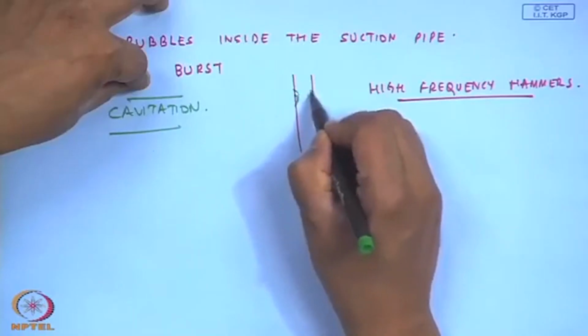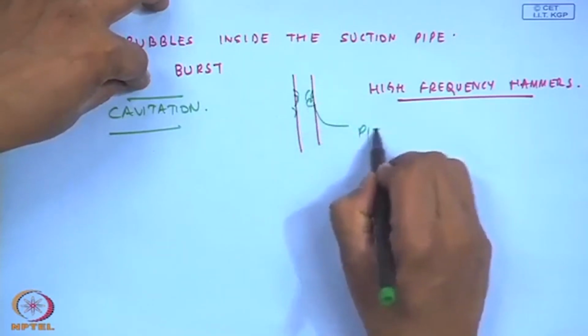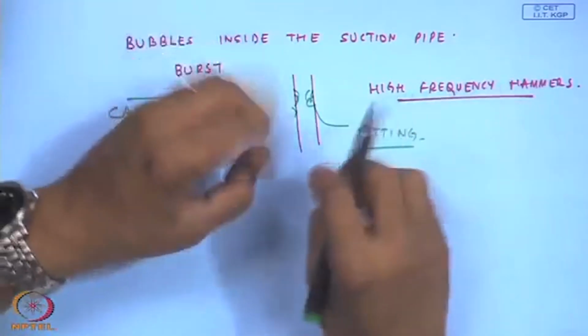The inner walls will get pitted, because when the bubbles burst they release energy as if they are hitting. If this goes unnoticed they will weaken the structure, and then a lot of the surface will become weak, and it may eventually break.